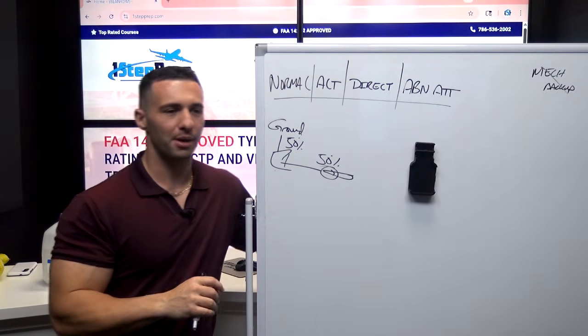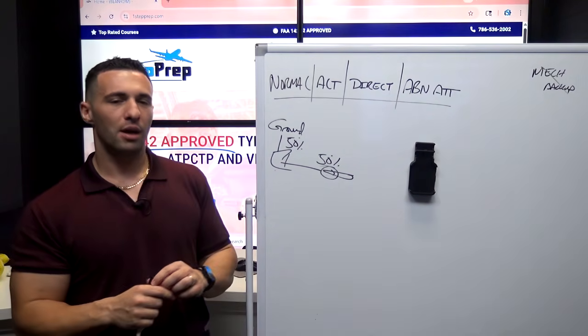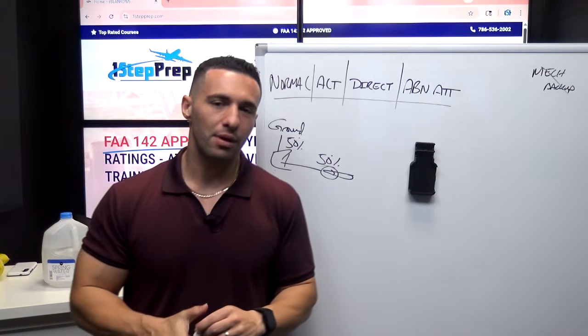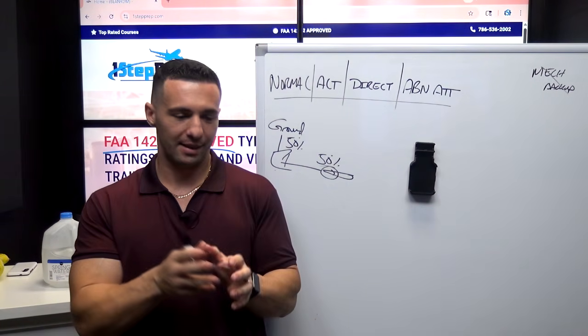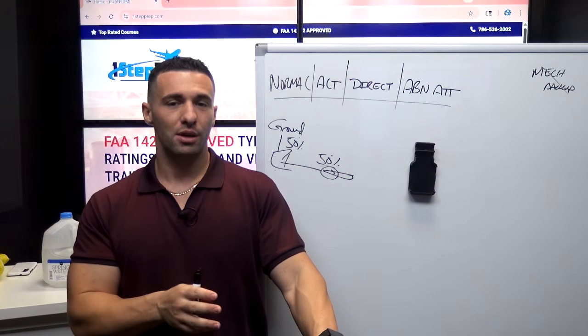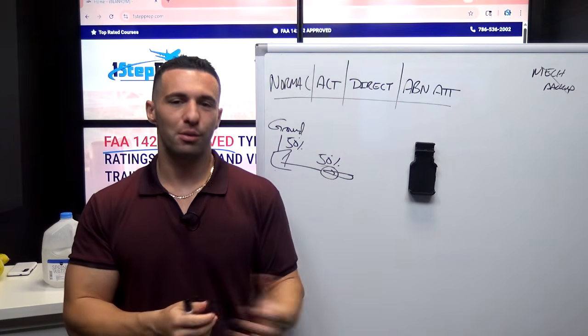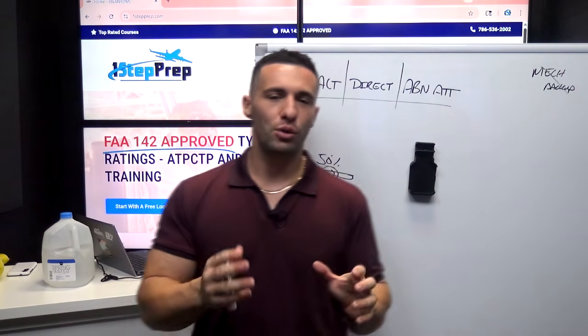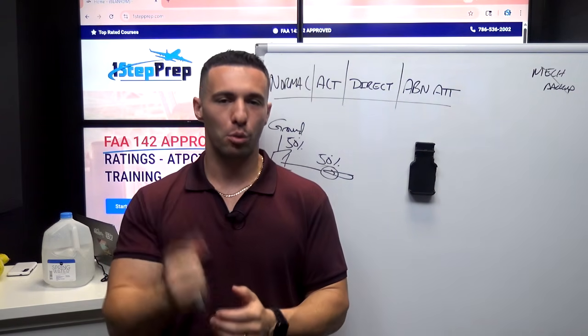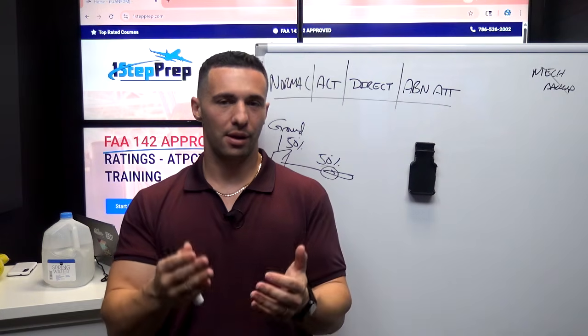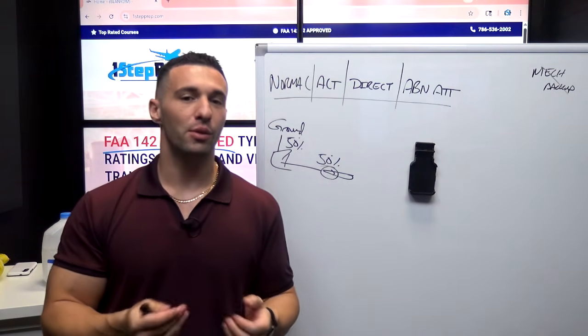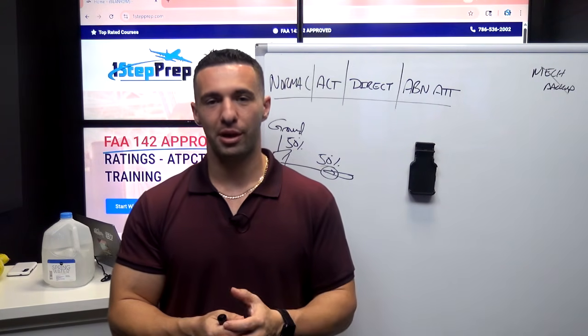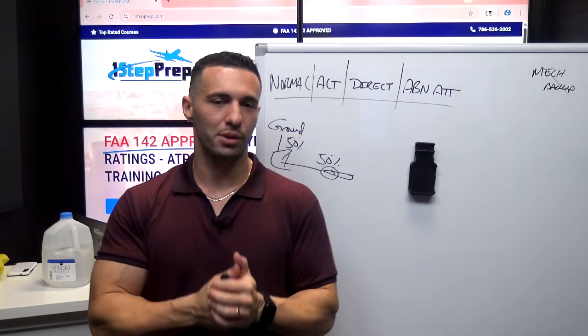Now I'm going to share something about the flight control check. Be very mindful that on your flight control check, you're looking at the flight controls page, the architecture, as Airbus puts it, when it pops up and you move that side stick. Yes, you do have the crosshair on the attitude indicator that will move. The crosshair being there is also a telltale sign that you're in ground mode, because the crosshair disappears once we're airborne. We transition to flight mode, which we're going to look at.